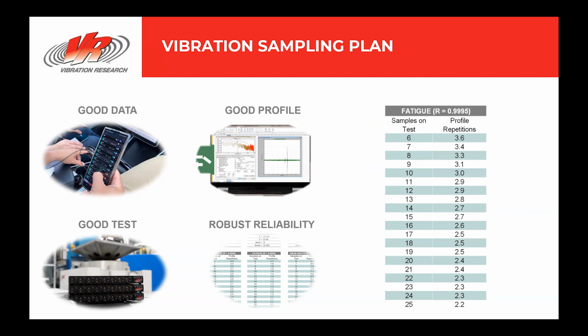They are most applicable to product validation at the process confirmation stage, but can also be used earlier in product development to aid with reliability growth, modeling, or as part of a product screening after production has started. While testing multiple product samples to failure with a field correlated test profile is the best way to predict reliability, this is not always practical due to time and/or lab equipment considerations. Sampling plans are based on demonstrating reliability by testing a predefined number of product samples for a set duration with no failures. This is called a success run test.